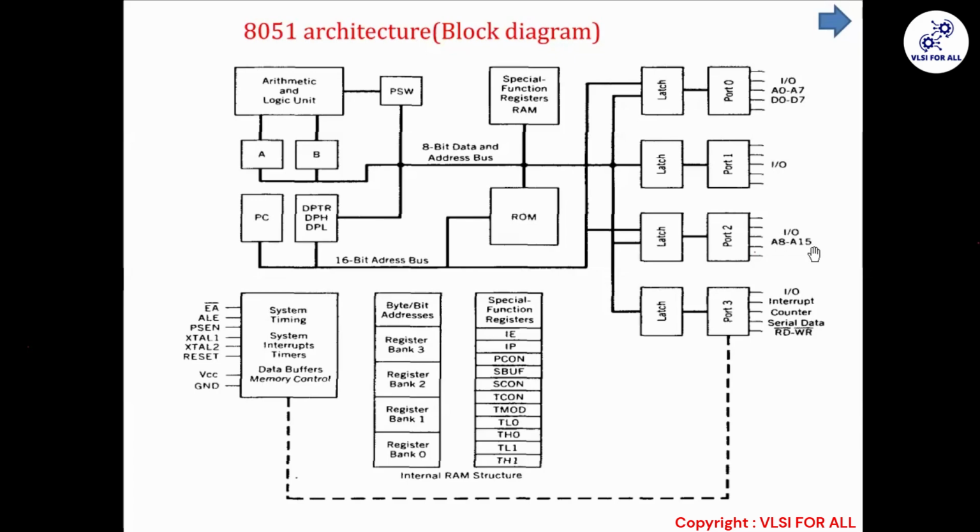Means the 8 MSBs are taken from port 2 and the 8 LSBs from port 0, either given out or taken in. So we are dealing with a 16-bit address, either external or internal. I'm trying to emphasize again and again that we deal with 8-bit data but a 16-bit address. Means more program memory compared to the data memory.